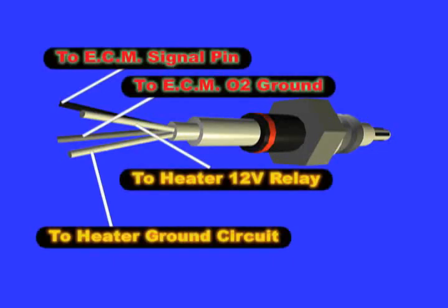If the O2 signal stays low, but changes when you goose the throttle, then you have a lean condition, such as a vacuum leak, loose vacuum hose, leaky brake booster, or other type of vacuum leak. If the O2 signal is always high but changes with the goose test, then you have a rich condition, such as a leaky injector, filled evap canister, or stuck open EGR valve.